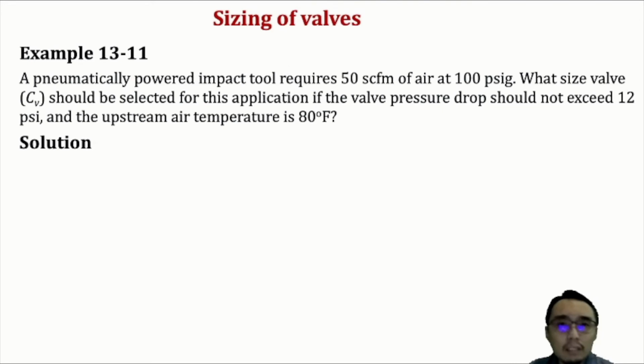Okay, so it is important that the valve be properly sized in the pneumatic system. If valves are too small, excessive pressure drop will occur, leading to high operating costs and system malfunction. Similarly, oversized valves are undesirable due to high component cost and space requirement.